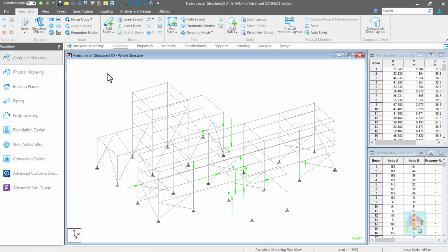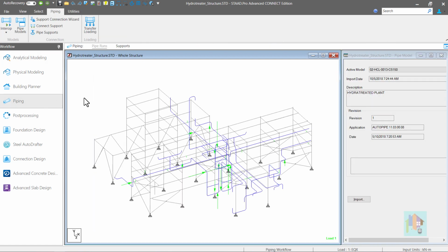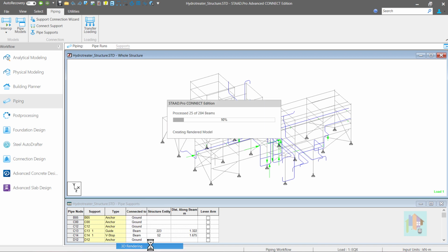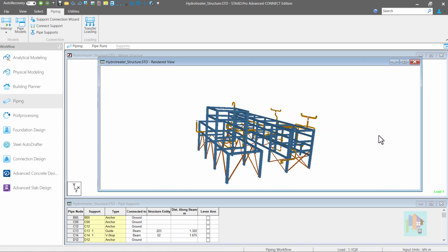Do you know, using the wind load generator, we can generate complete wind load specification for any unclad frame structure? Consider this pipe rack structure. It is an exposed steel frame without any cladding, which supports several pipes with variable diameter at different levels. These pipes are modeled and analyzed in AutoPipe. Then that information, including support data, is imported in STAAD using the STAAD AutoPipe link. As you can notice, all these pipes are correctly placed on the frame with proper connection.